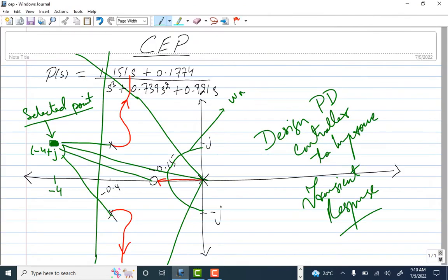notebook here. Okay, so this is the transfer function. Look here, we have a pole here, we have a zero here. So this is the requirement of steady state. This is overshoot. This is my root locus. So if you look at it, this is the rise time. If you look clearly here, we have to find something here so that we can satisfy that transient response. So now the issue is that we have to move this root locus in this direction.